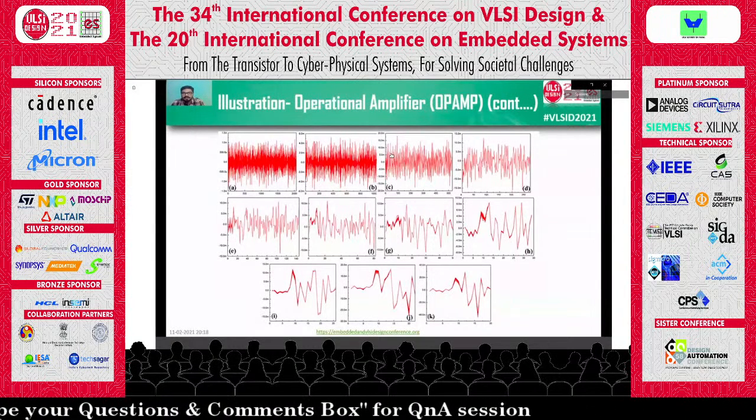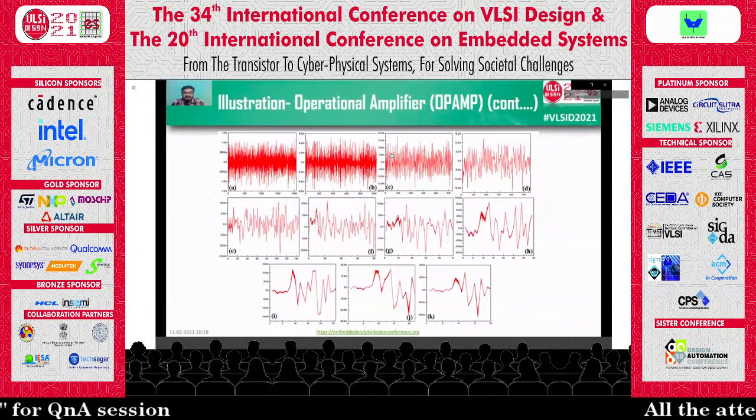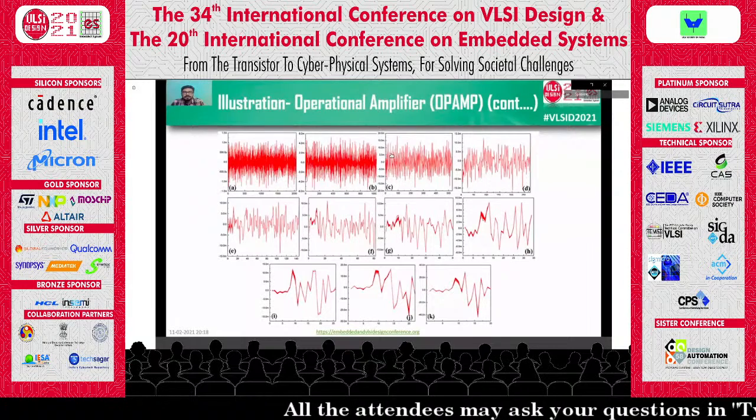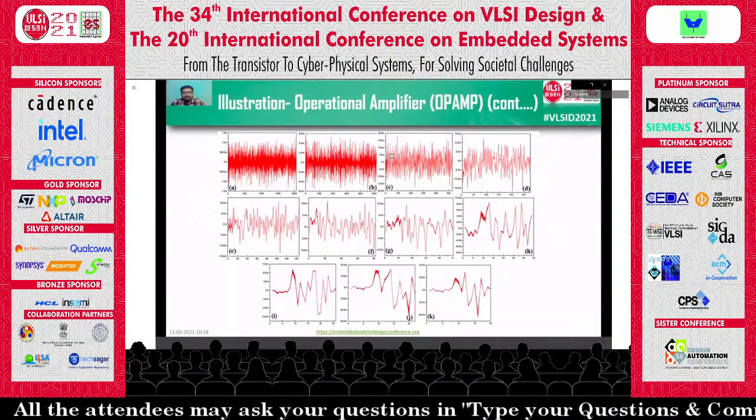signal is 250 MHz. At the first level, the signal containing 4096 samples is passed to the high pass filter and the low pass filter. The outputs are subsampled by 2. The output of the high pass filter is denoted as the first level of DWT coefficients shown in the first figure. The 2048 samples depict the signal in the range of 125 to 250 MHz.